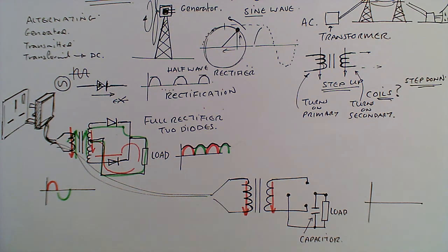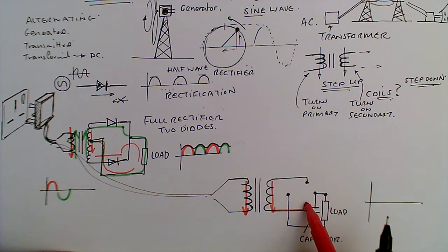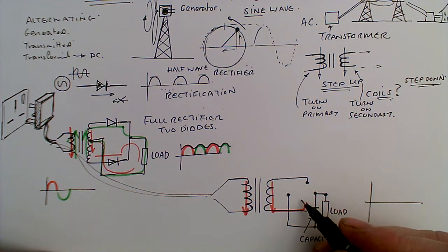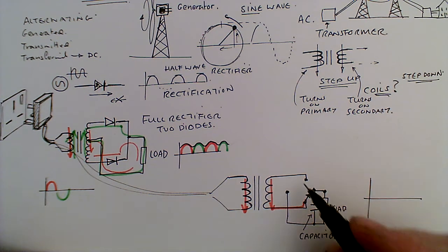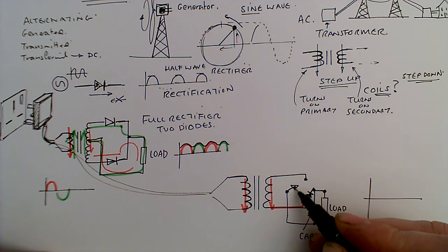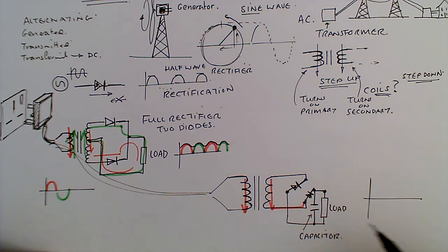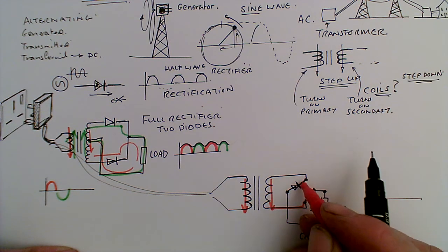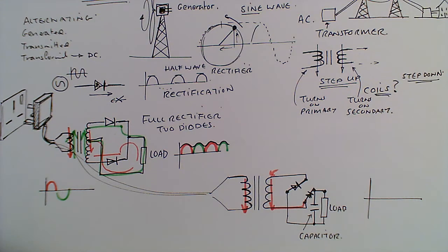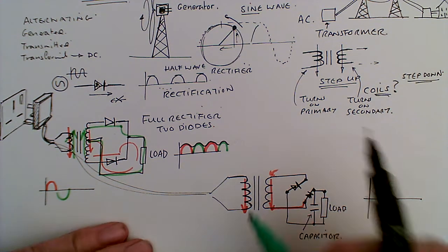So what we've got here is the electrons can go along here and they come to this first junction. There's a diode here that allows them to flow. So they can flow up here, through the load, around, and there's another diode in parallel there, allowing that circuit to complete. So it goes through there, around there, up there, and back over the top. That's the first pair.